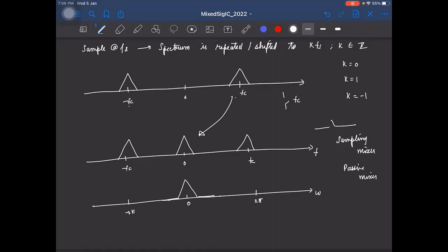Well, of course, we not only will be sampling the signal, we'll also be sampling the broadband noise, right? So we'll have to ensure that we are filtering and making sure that the frequencies from which the noise can alias back are attenuated by a reasonable value.